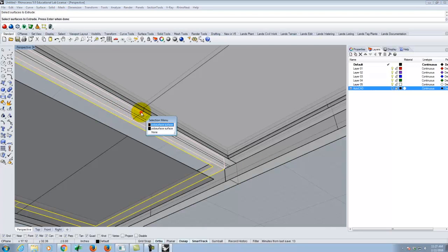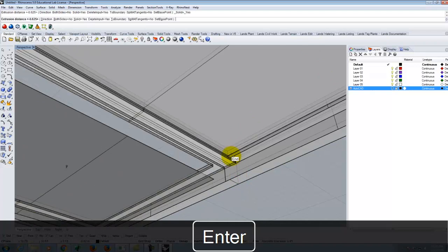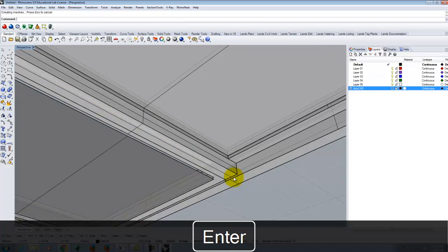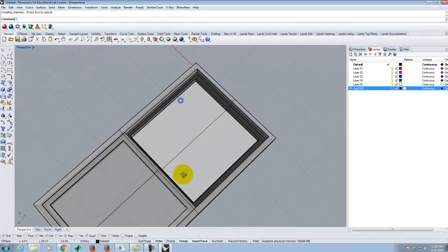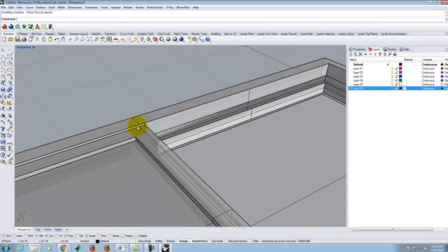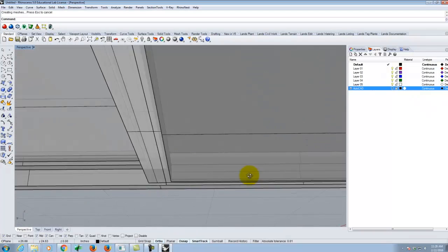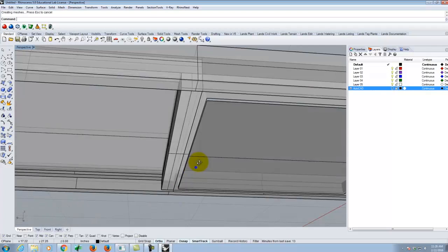There and there and there. Okay. And I'll go ahead and press enter, and we'll drop them down so that they are negative 1.5 inches as well. And there it is. Now notice that when I did the math, I gave myself a little 1/4 inch reveal there, and also on the back side underneath here. Right there. It just cleans it, makes it look a little nicer.